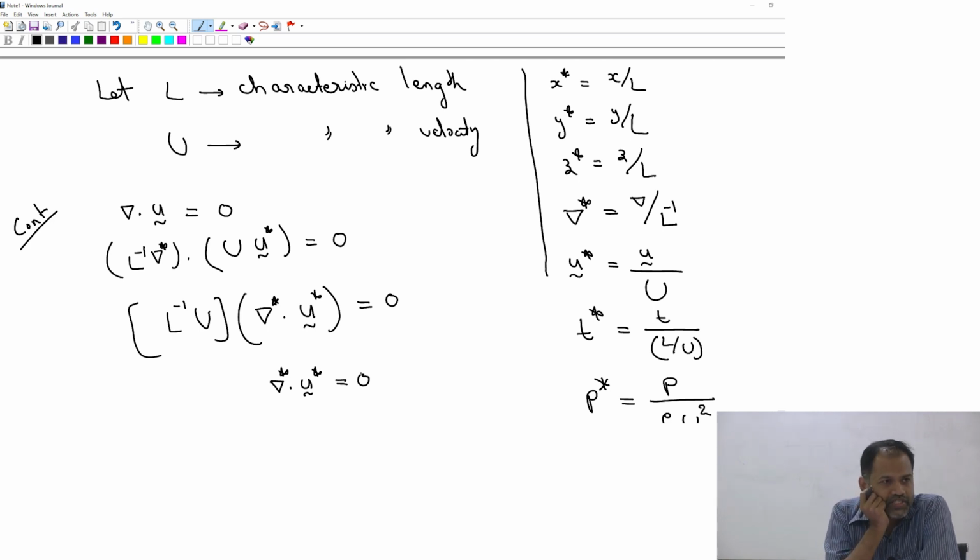Okay, so the continuity equation written in the non-dimensional form did not bring in anything new. All the variables remained as such, except that they have become non-dimensional. There was no non-dimensional parameter that came up during the non-dimensionalization. If you remember, we had done something very similar when we derived the equation for flow between plates or tube flow, where we did the non-dimensionalization. Does anybody remember? We had a differential equation. We non-dimensionalized it with a characteristic length, a characteristic velocity, and we ended up with something very similar. There again, we did not have any non-dimensional parameter. So this is something very similar.